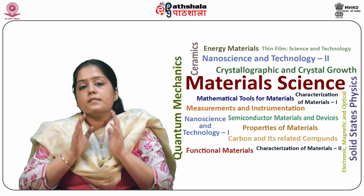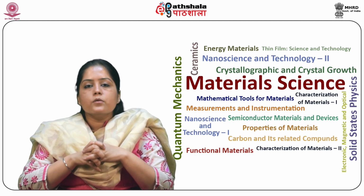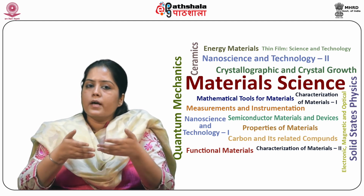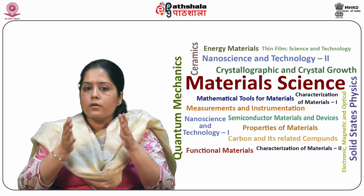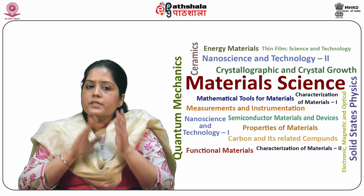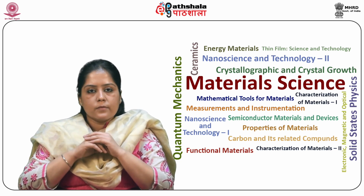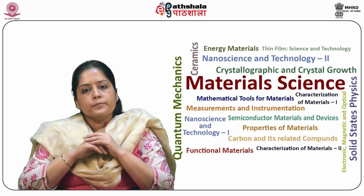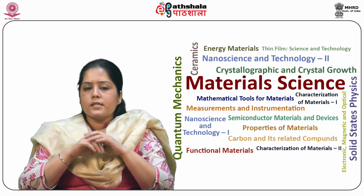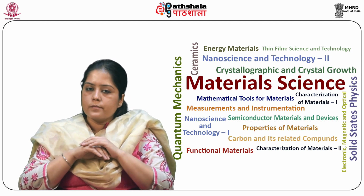So the present day technology uses 8 inch or larger pseudo square wafers of around 200 micron thickness with an efficiency of about 15 to 16%. The energy payback period of such cells is about 3 to 4 years.